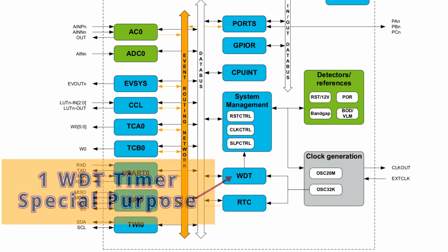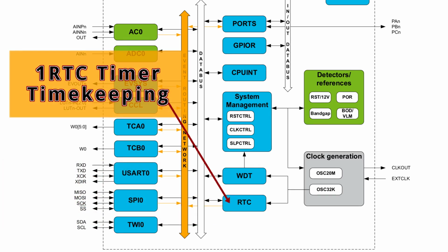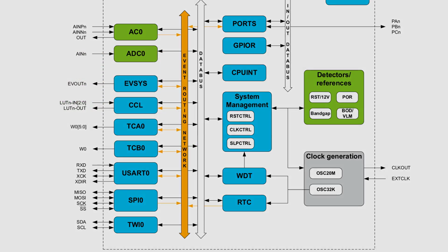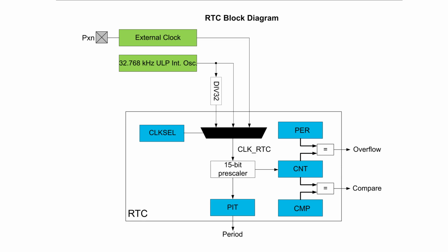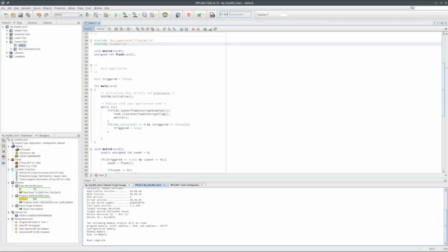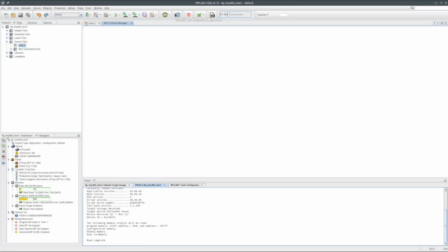But what I didn't look at was the RTC counter, as it seems to be clocked from the low-frequency oscillator, but I should have. This looks to be a perfect peripheral to keep a nicely timed program loop running. So I'm going to start by digging into the RTC Timer module. It can generate up to 3 interrupts, so instead of having to keep time with software, I can just let this RTC module keep track of it, with some limitations. Let me fire up the MCC and see what it looks like.